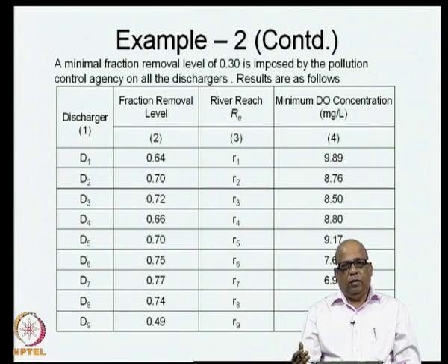Now, we will go to a simpler, more general problem where we will often be using the fuzzy membership functions. In the case of reservoir operation, you will have storage targets as well as release targets. Typically in deterministic optimization, when you are doing reservoir operation, you would minimize the deficit of the storage from its target, typically the sum of square deficit plus the deficit arising out of the releases. So, this is how you would have determined the reservoir operating policy.